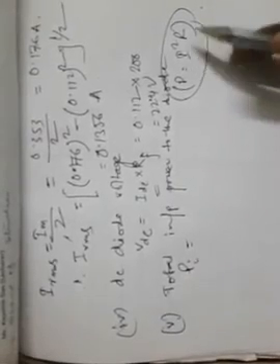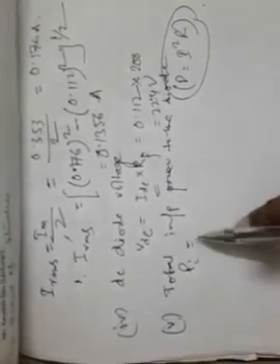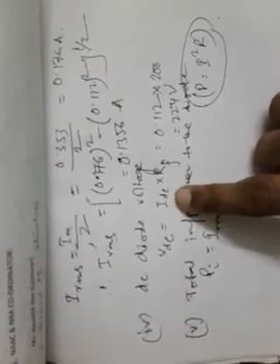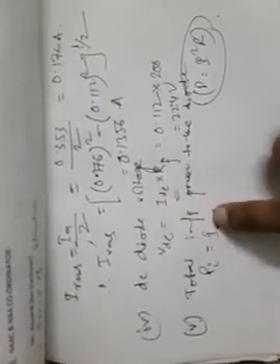So now we have, as we have calculated this I through the diode and RF is given, the diode resistance, we can easily calculate Pi, the input power to the diode. The current is obviously having some AC component, so we should be considering IRMS and not IDC. Just check the dissimilarities between these two calculations.